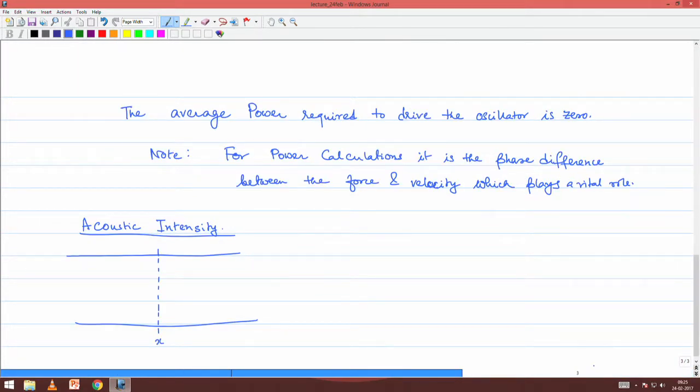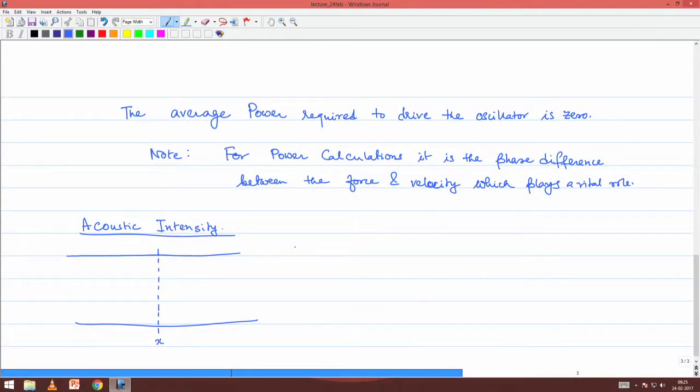And what is happening here is that on this dotted line, though it is not visible with our naked eye, there are acoustic particles sitting. Particles immediately to the left of this dotted line are pushing these particles sitting on the dotted line with a force per unit area equal to pressure, and these particles are now moving with a velocity v or ux if you may call it, right. So, as a result the same situation is happening. So, we could do a power flow calculation exactly in the same manner, and that leads us to the concept of acoustic intensity. So, acoustic intensity technically is defined in the following fashion.